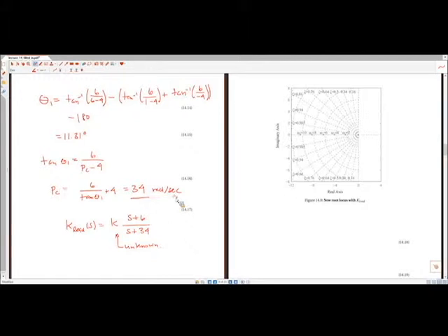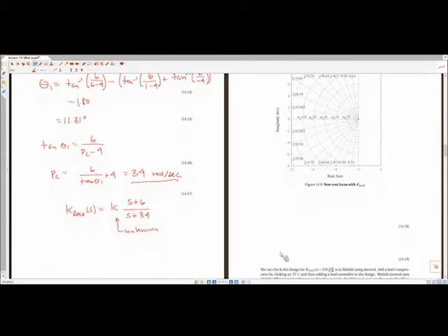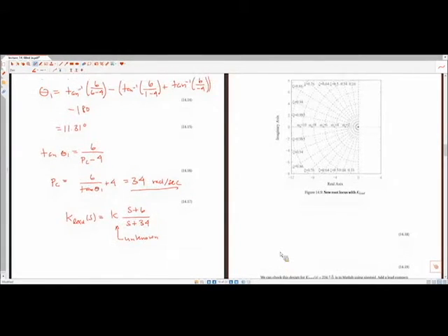Right here. And so now we have determined two of the three parameters of a lead controller: the zero location and the pole location. Yet to be solved for is the K, or the gain on the entire system. So that's where we're going to start off today's lecture, calculating this gain. Before we do that, though, I want to plot the root locus for this system, just to have a remapping of it, and to see another example with root locus plots for your notes.